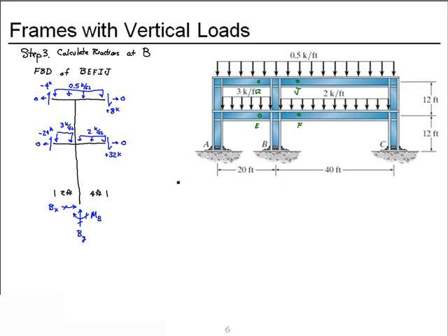Now we're ready to apply equilibrium. Sum forces in the x direction. We'll choose to the right as positive. We have the reaction Bx, but notice, because of our assumptions, all of the normals are 0. So our reaction Bx will predict to be 0.